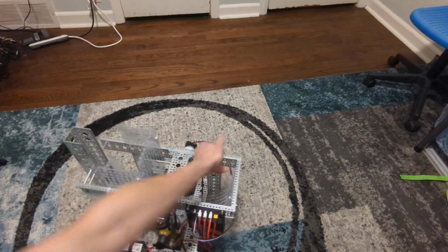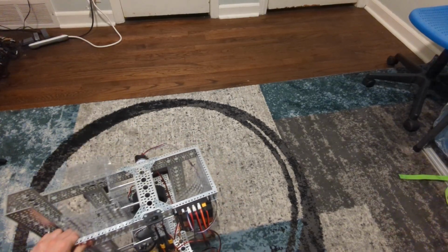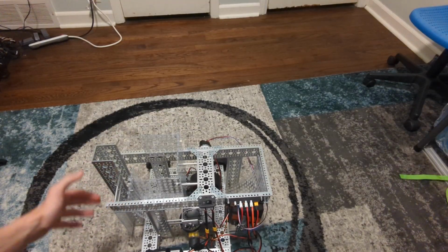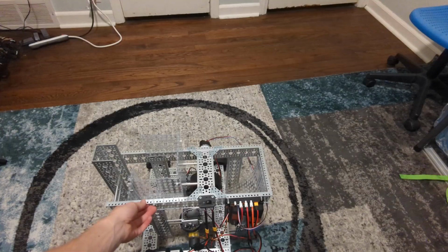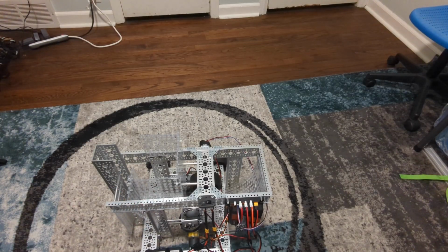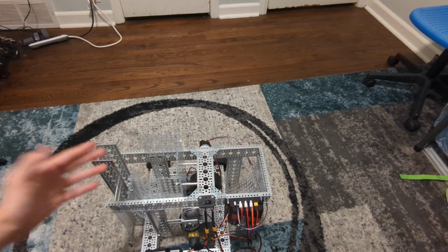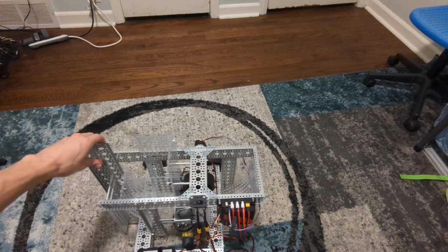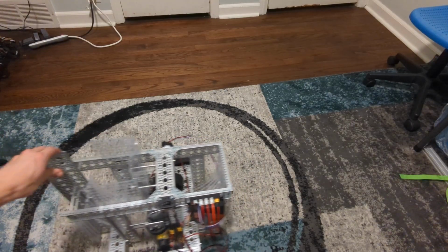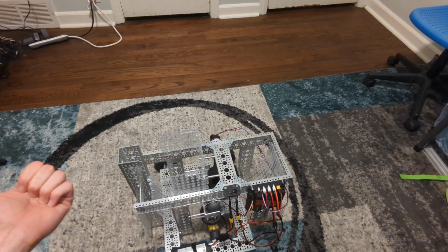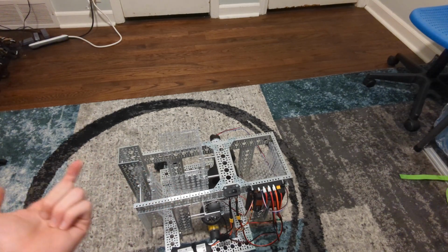So if I want it to turn less, I have two options. I can make it turn slower, or I can make it turn for less time. I generally favor turning slower. However, in autonomous, you only have 30 seconds. So if you have a really complicated auto routine, you may need to keep that in mind. But those are my options. If I need it to drive further or less far, I can play with how fast it drives.